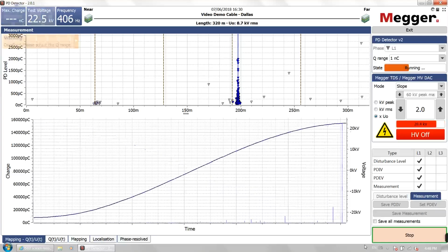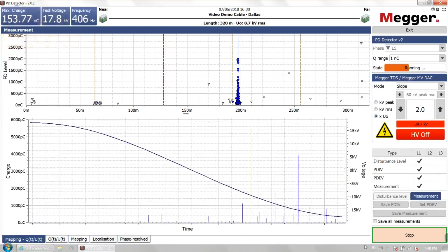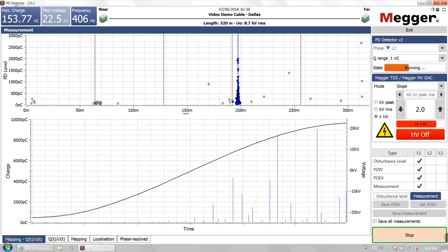And we're starting to have some snaps inside the box here. That's what these overflow ranges are. And we're also starting to get some partial discharge on the termination. So we might not be able to get this without having a breakdown inside the box.